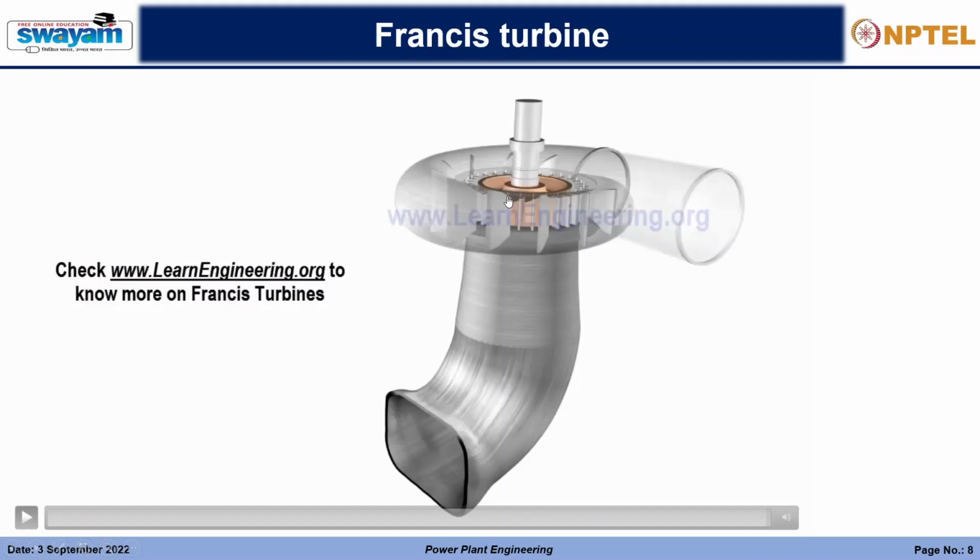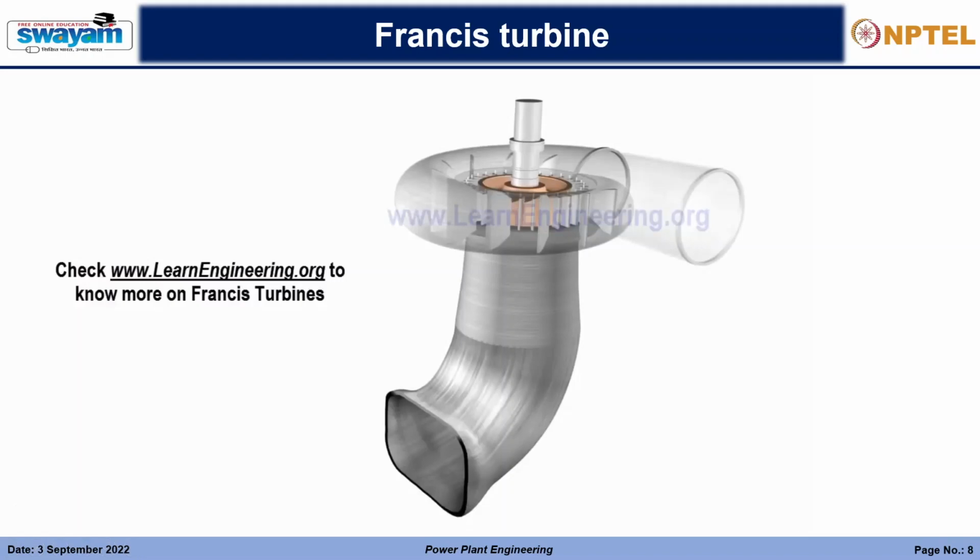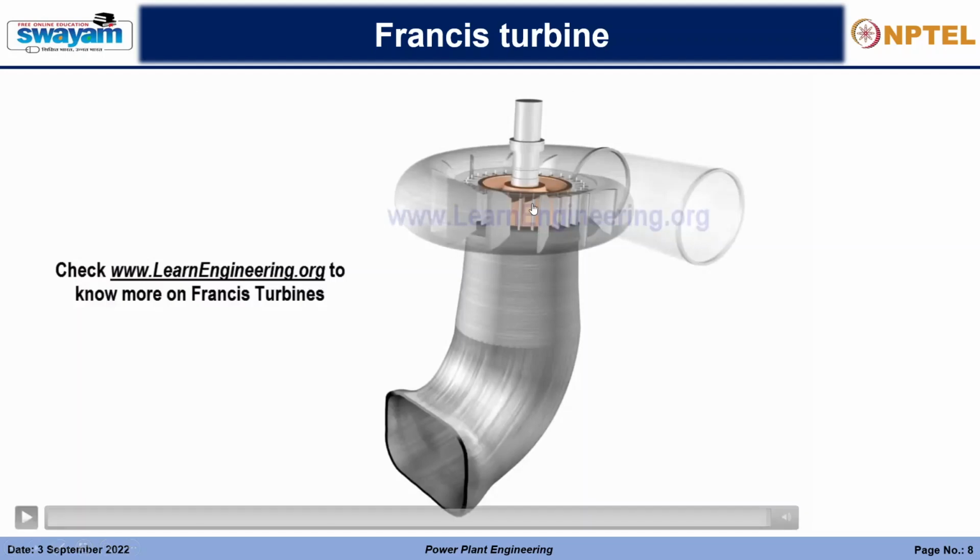Again, there is an aerofoil. These runner blades are actually aerofoil shaped, which is imparting some part of this tangential force due to the pressure difference, and hence this is called the reaction. Okay, and as it is also having a dent towards the lower portion, it is also causing impulse.